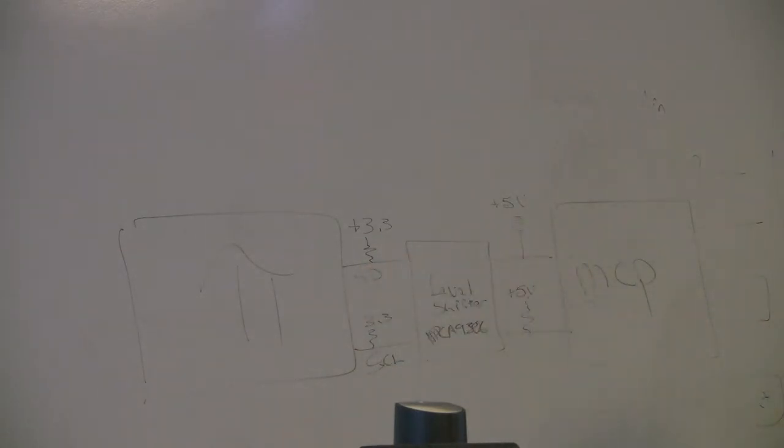The data sheet for the MCP will also tell you the minimum logic one. Exactly. I've never seen that logic one lower than 3, you know, every time I've checked it out, it's always, I'm not saying 2.7 or something, yeah, you're right. It'll probably work as long as they're close together and there's not a lot of noise, but this might be a more robust solution.